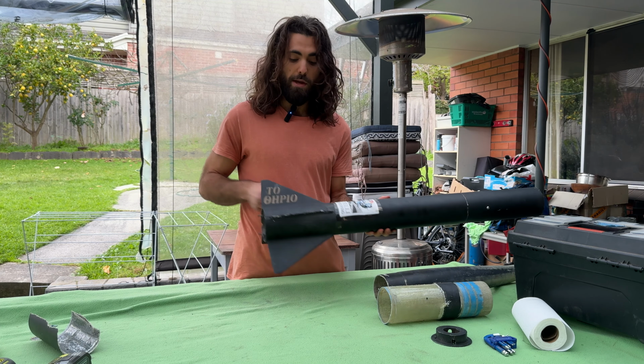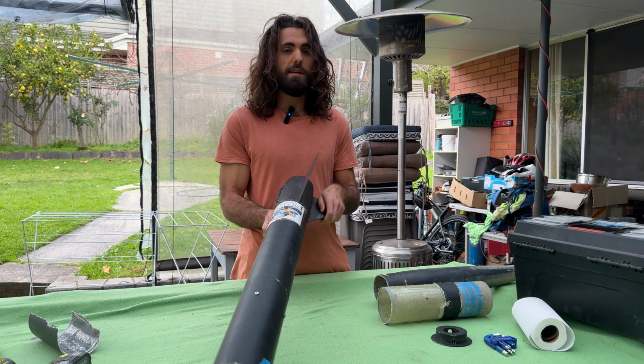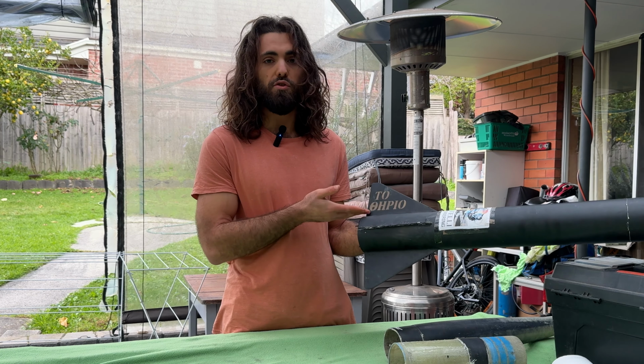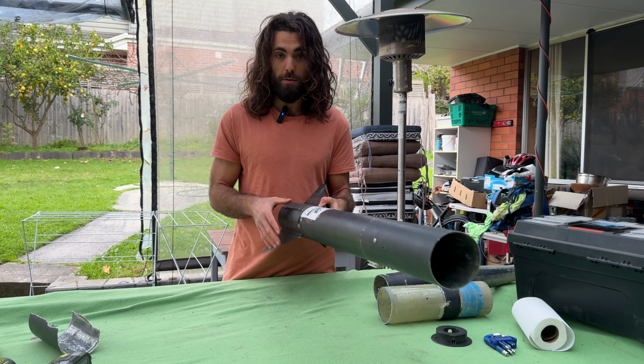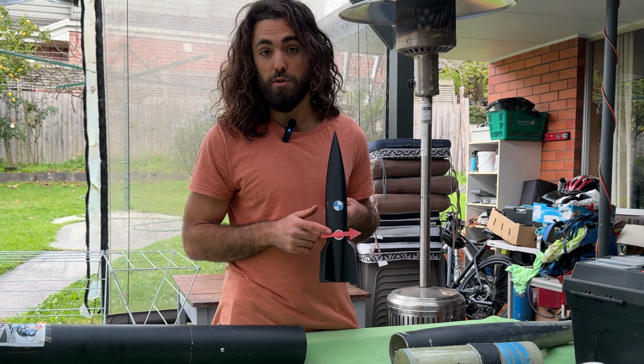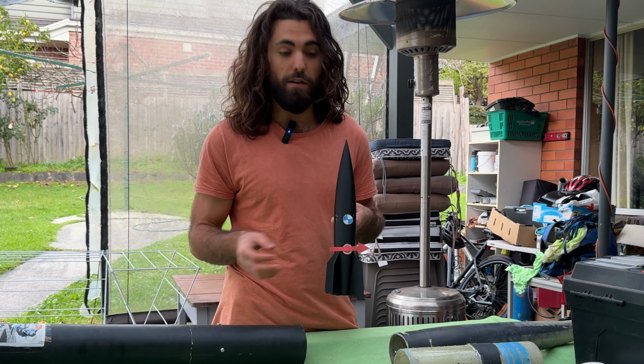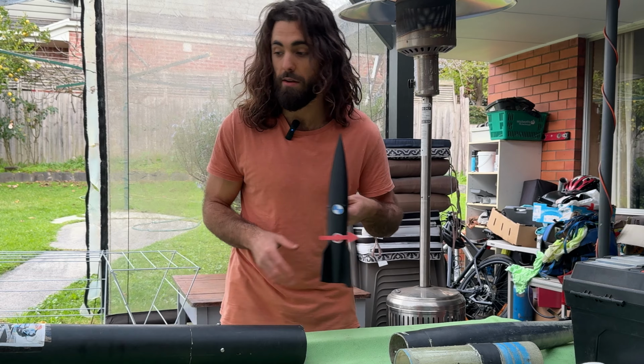Moving on to the end, we have fins. On the surface, fins seem pretty dumb because you're just adding extra mass and extra drag for your rocket to deal with. But they have a pretty critical purpose. Remember how we were talking about center of pressure before and how we said it was an average of the distribution of the surface area? Well, that's what these do.